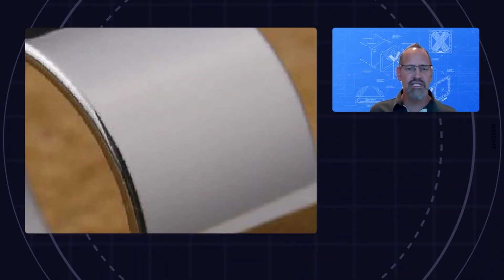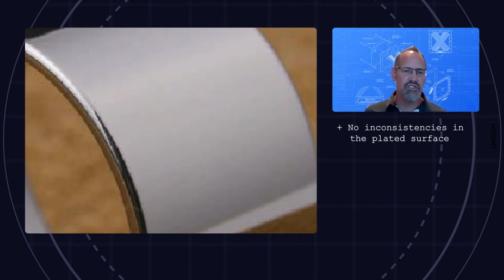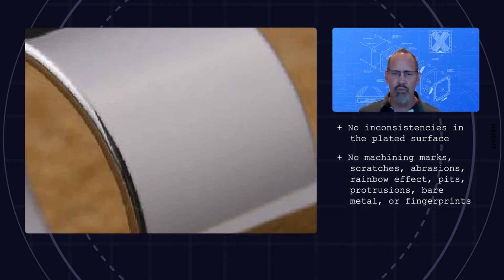Now let's look at some acceptable workmanship standards. The first image illustrates the ideal finish that an end customer should see. There are no inconsistencies, as well as no machining marks, scratches, abrasions, rainbow effects, pits, protrusions, bare metal, or fingerprints showing. Image 2 is an example of the rainbow effect apparent with zinc plating.